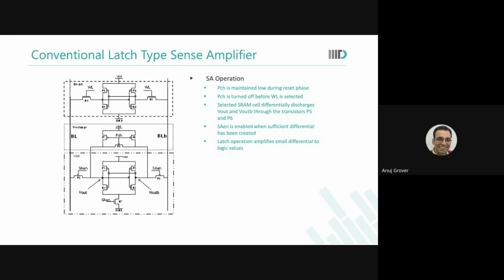Now for this metal 2, first the wire length has become different. Second, suppose metal 2 had a gradient in etching. Now this wire will be more resistive than this wire. Okay, they are very, very close, I understand. But let us say there was another signal running from here on the bottom side. Now that signal is causing a coupling to this one, but not to that one. Are you able to see this?